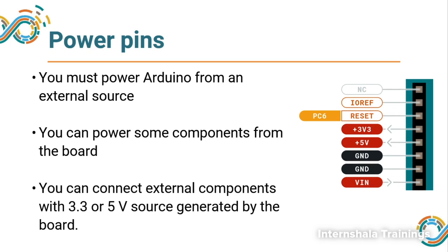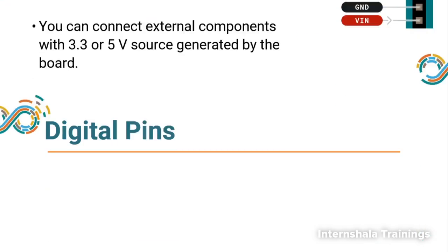These pins definitely have some limitation in terms of maximum current that can be provided. The maximum current is a few milliampere, so they are good to glow an LED, to control an LCD, but not good for running DC motors or anything which requires high current.